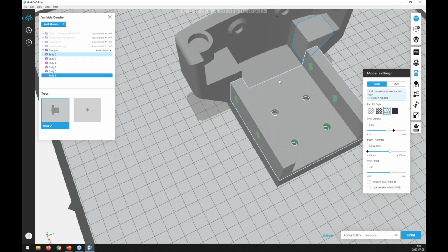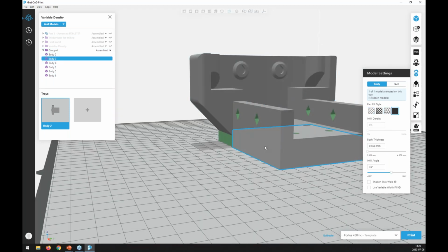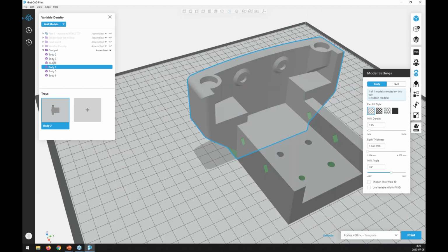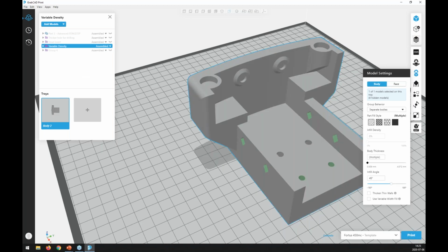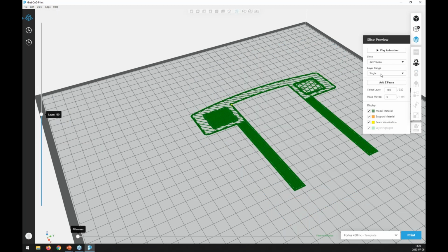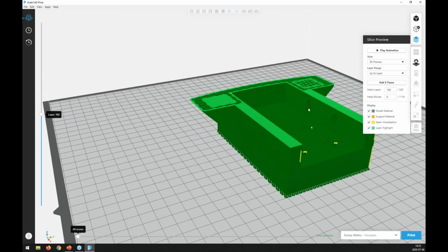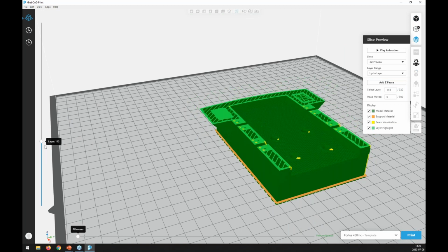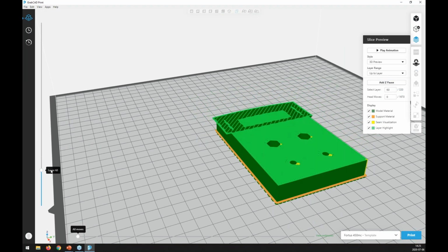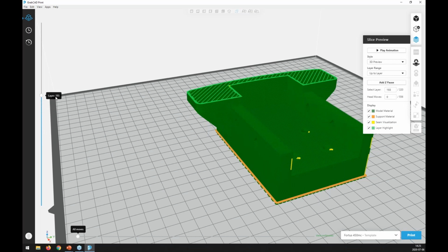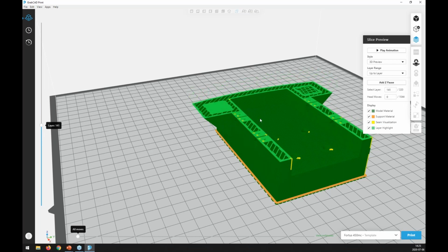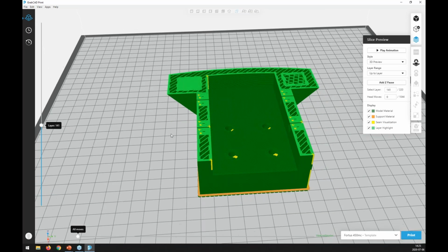And by changing all the bodies, giving them different settings, when you go back to the slicing and show the model, you will notice that the different regions of the parts have different fillings. This of course is just an example, but you can play with creative construction of the CAD data and the different bodies to make the parts variable density.